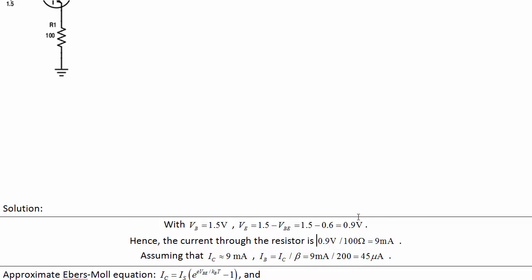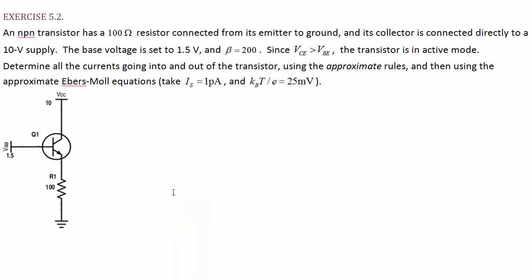All right, so the Ebers-Moll equations, what does this get us beyond doing that? The only advantage of the Ebers-Moll equations is it says, well, the base-emitter voltage, we said that's approximately 0.6. It's probably not really 0.6. So let's figure out what it would actually be by setting up some equations. This is going to be basically like what we did with the diode and load line. So we'll say that we've got a VBE, and we don't know exactly what it is.